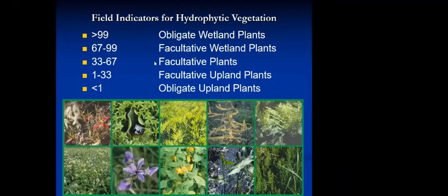As per the records, these are some of the indicators of wetland. Next, along with this wetland hydrological characteristics, we need to answer with the hydrophytic vegetation. What type of plants? From the list of plants, we have to list out which are the wetland plants, with the help of botany people. Then some areas, if more than 99% of the vegetation is hydrophytic vegetation, what you call the obligate wetlands.